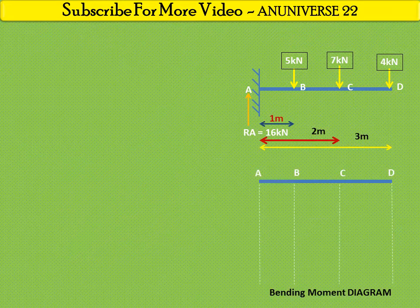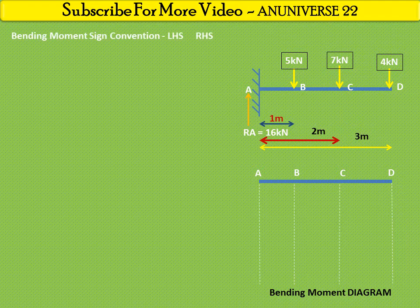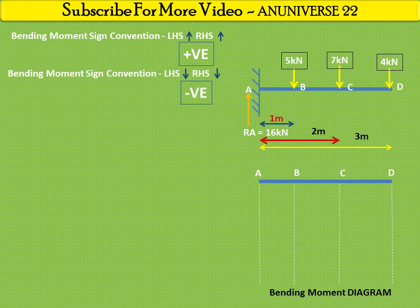Now we plot the bending moment diagram. First we learn the bending moment sign convention: when the left hand side and right hand side of the beam move upward, we take positive bending moment. When the left hand side and right hand side of the beam move downward, we take negative bending moment. Here we have 4 points A, B, C, D, so one by one we calculate the bending moment at these points.